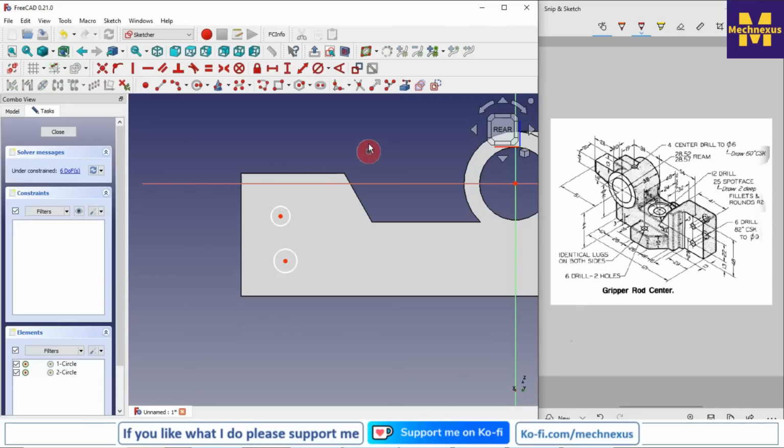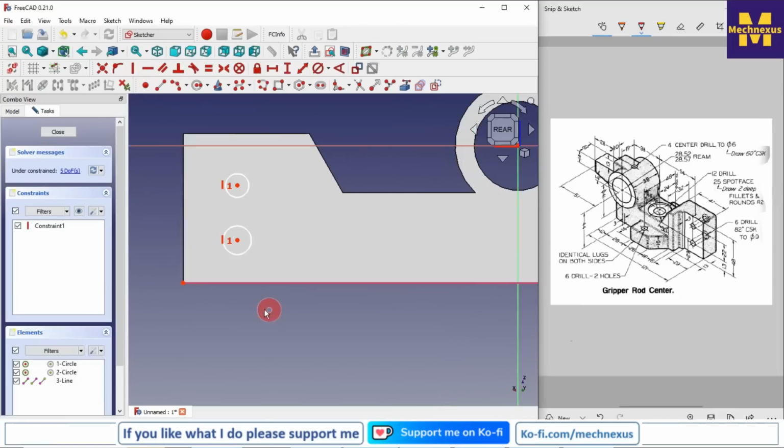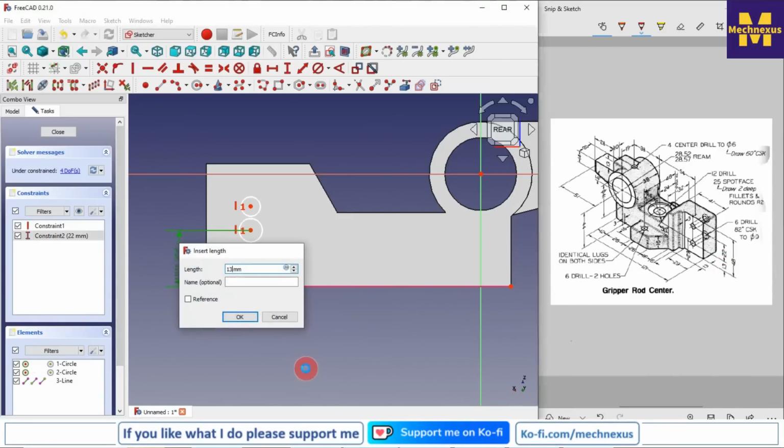So for this we will click on project geometry and we will project it, and before that we will add the vertical relation. Now select this point and this point, add a vertical dimension of 22. This is the 13 mm, so I will edit it and give the 13.